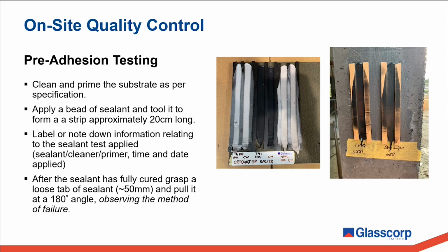the surface. When we do adhesion tests, we like to apply 2 lengths of foam tape and apply the sealant in between just to give you that clean, uniform strip to test. Obviously, if you're doing this, make sure that the surface is cleaned and dry before putting down any tape.